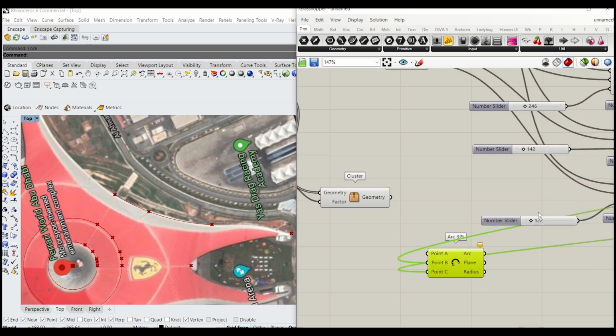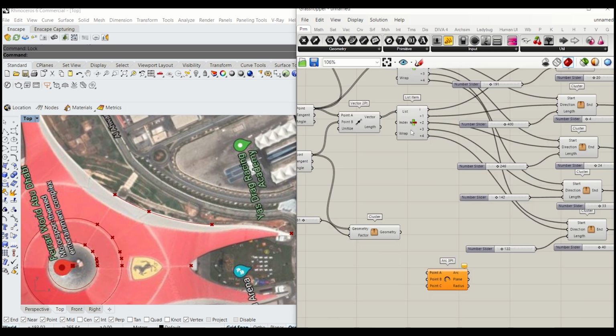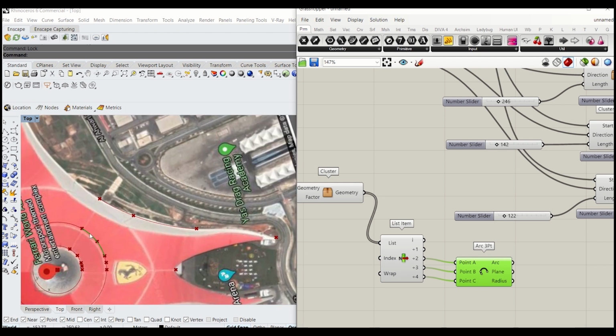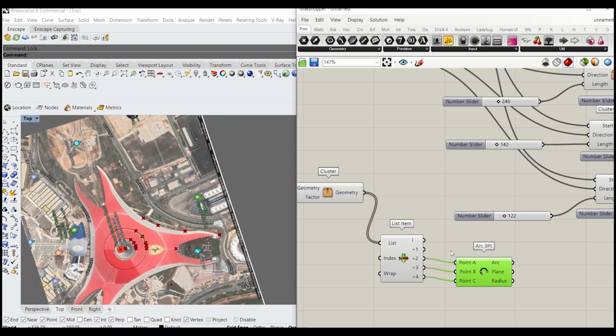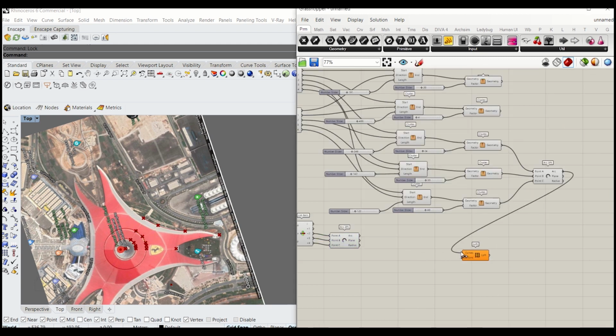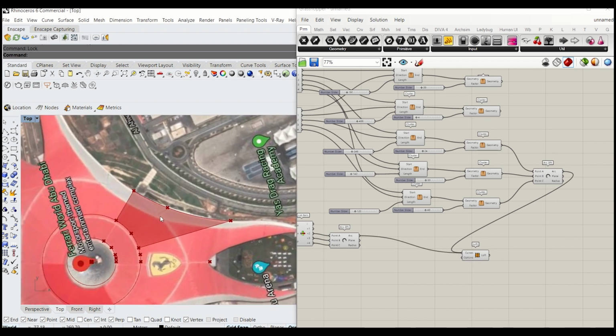So we'll have to disconnect that. You could just simply copy that too, because it's already got the 5 outputs. So we know if you input that, you will get 5 outputs. So we want to get 3, 4, 5. So 3, which is 2, 3, 4. That constructs a curve there. So if you loft these two, you will get that part of the roof. So let's type loft, connect that curve to that curve. So you got that section built.